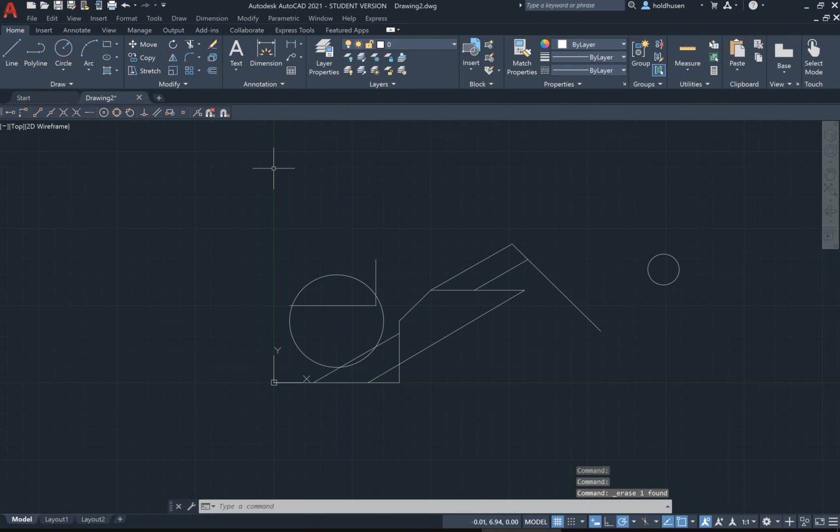So a lot of times you can draw lines that you're ultimately going to be deleting later. Call those construction lines. It's just kind of a way to do things that'll make your life a little bit easier. Now again, you could trim these, and typically I draw a lot of circles, and if I want to trim them, I can do that. I can just select the trim, and I can just say get off that little point there, or this little point there, and then essentially I have an arc like that.